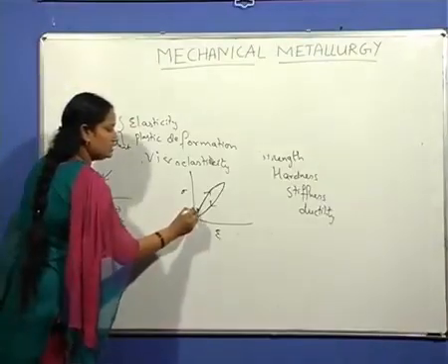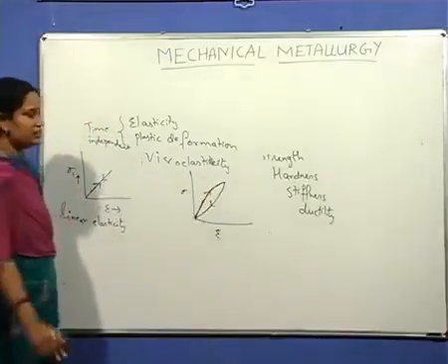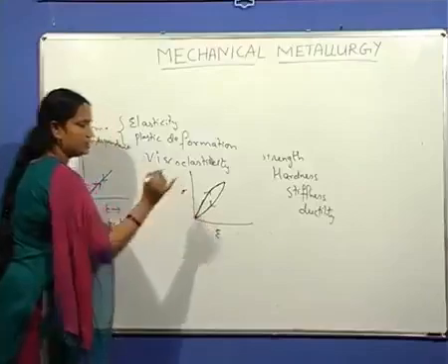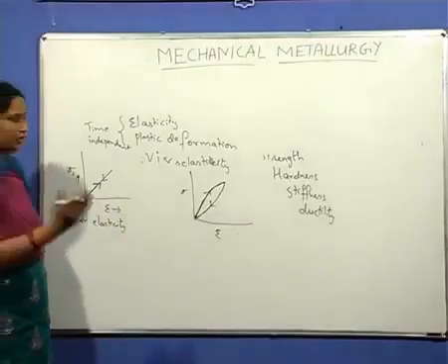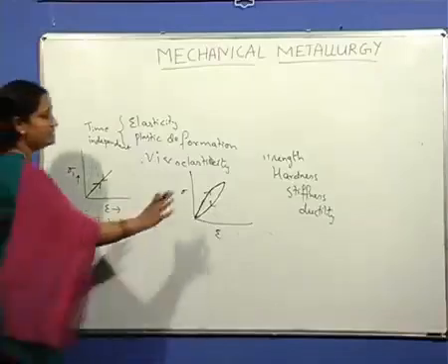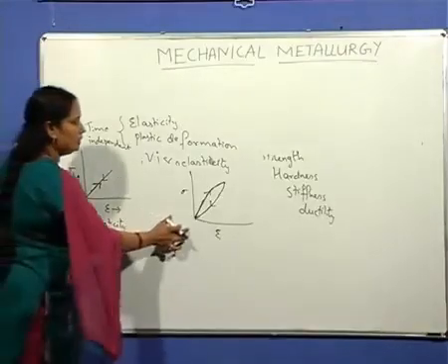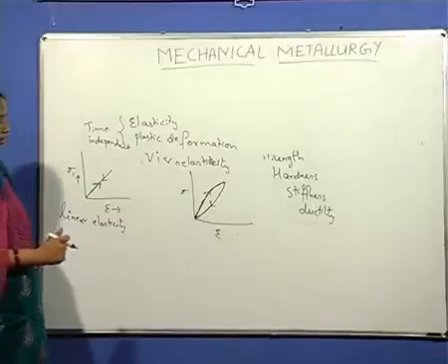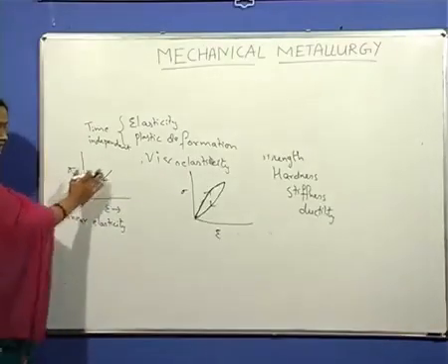Initially, the material undergoes some amount of linear elastic strain. Then the strain approaches some asymptotic value, and then upon unloading it follows a different path. The linear elastic strain that the material initially experiences recovers instantaneously upon the removal of load, whereas the viscoelastic strain recovers very sluggishly with time. So this is an example of the stress strain curve for a viscoelastic material, or this is known as viscoelasticity. In linear elasticity, the loading and unloading path follows the same path.